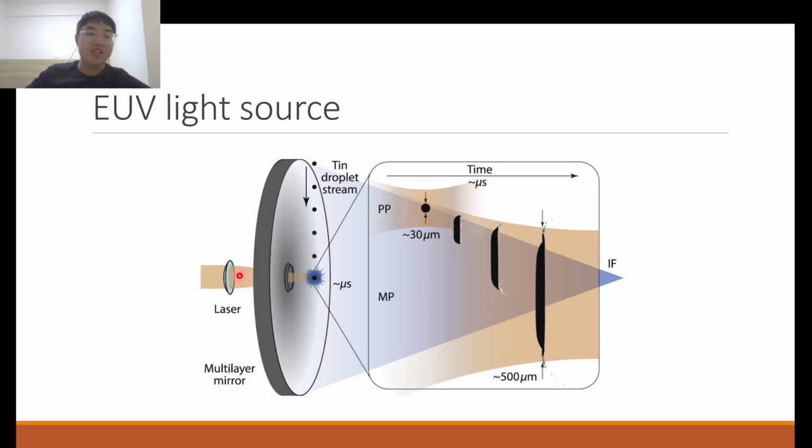And I think the energy efficiency is higher, because when you have a laser hitting your tin droplets, light is not always absorbed, it can be reflected. When some of the laser light is reflected, it represents a loss, an inefficiency, because not all of the energy input is used to excite the tin droplets. So theoretically, if you use the electric field, you can more efficiently excite the tin droplets, thus resulting in a more efficient EUV light source.